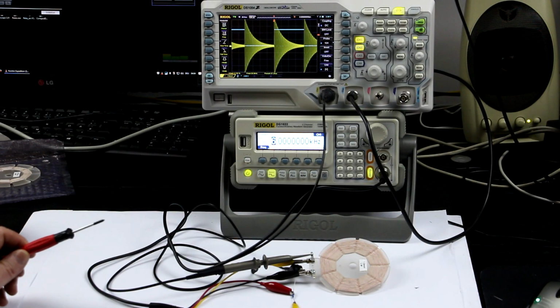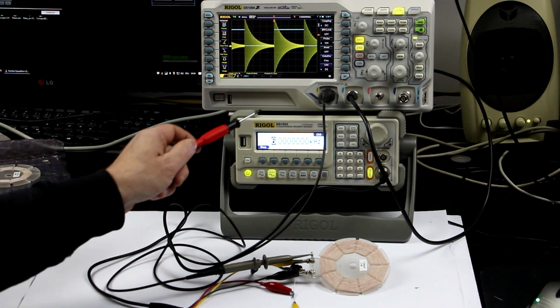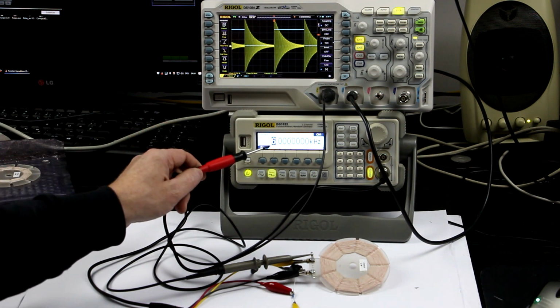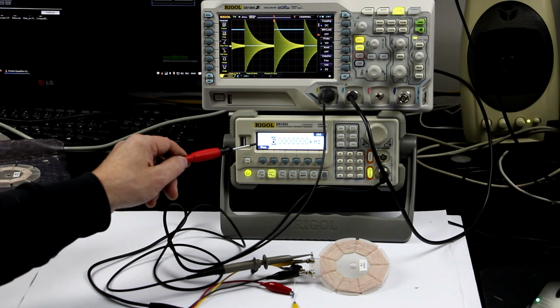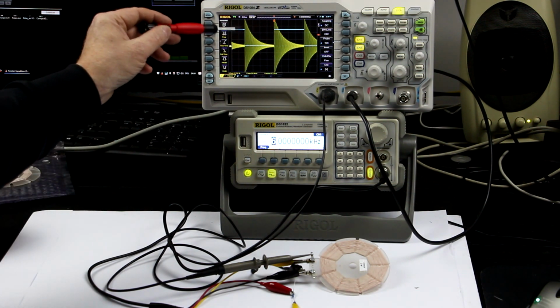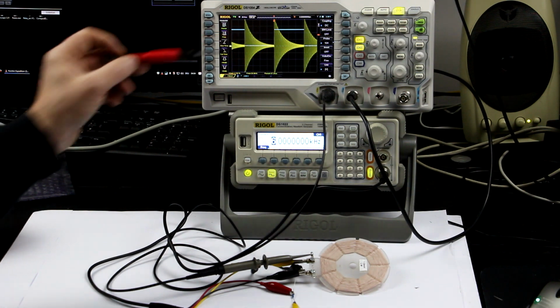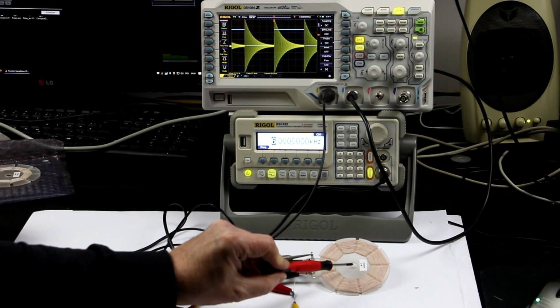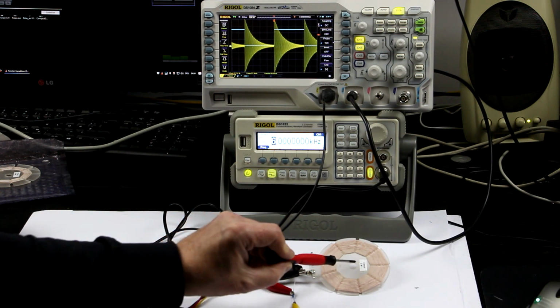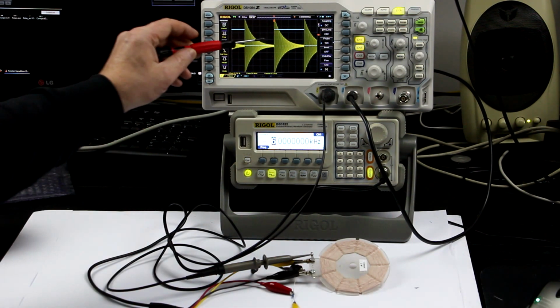So here we have an overview of the test setup in reality, just before we take a close-up of what's happening on the screen of the DSO. You can see I've set our Rigol function generator to output a 6 kilohertz square wave, and you can see the square wave here in blue. And at every pulse of the square wave, no matter if it's the falling edge or the rising edge, the tank circuit here, which consists only of this spiderweb wound coil, but with the parasitic resistance and parasitic capacitance, is excited.